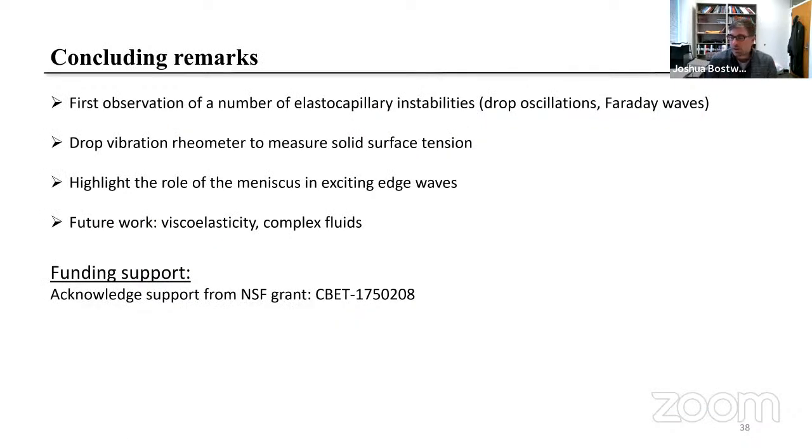So that's it for this talk. I want to end with a few concluding remarks. We're really interested in analogs of classic hydrodynamic instabilities, and we've made the first observation of a number of elastocapillary instabilities, namely drop oscillations and Faraday waves. We're using this to introduce the concept of the drop vibration rheometer to measure the solid surface tensions of these soft gels. And lastly, we highlighted the role of the meniscus in exciting these edge waves in complex materials and how that gave rise to mode mixing phenomena.